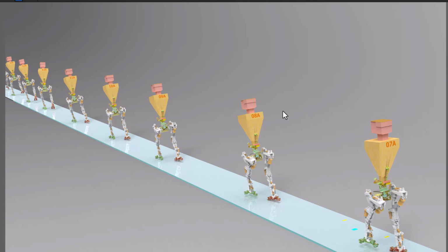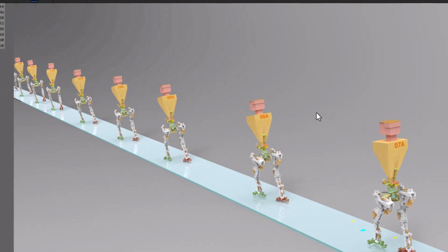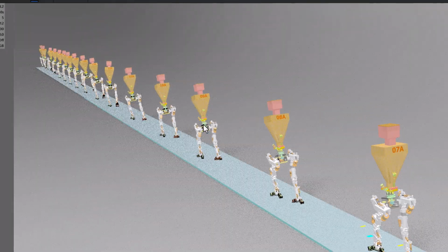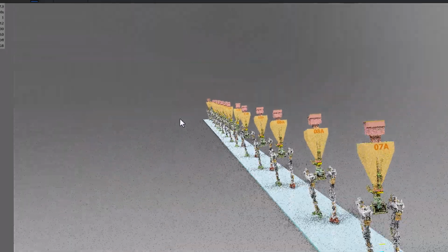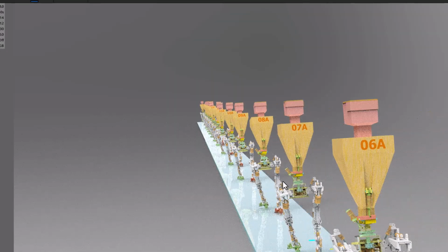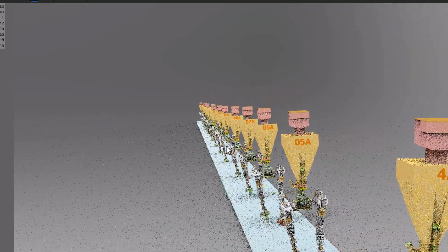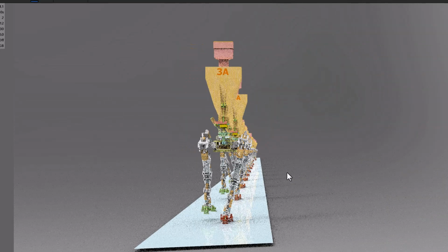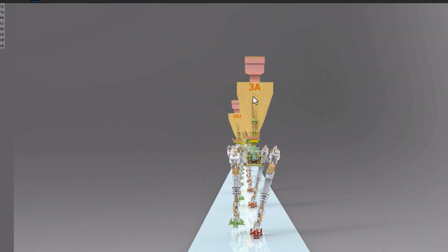And of course, we always want to switch out just for a second or two. And we have our little robots here spaced out so we can get behind them and look at how they tilt. For example, when the robot has the right foot on the ground, you can see that the weight of the robot is over the right foot, and the right leg is adducted, alpha delta. It's adducted to bring the left foot under the middle of the robot, whereas the left leg is straight down.